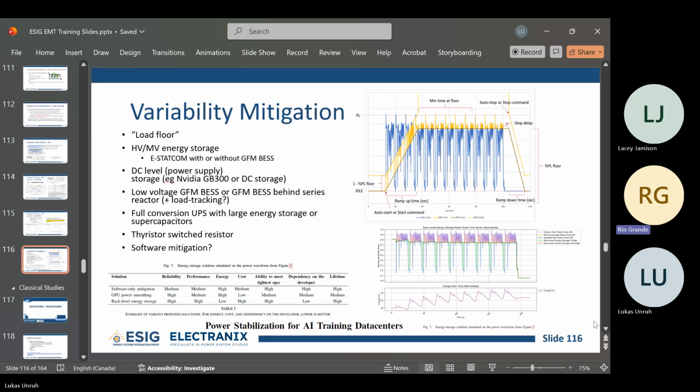I went through a bunch of IBR data through the alert process, and you'd be amazed how many exactly 74.9 megawatt IBRs there are out there, because the NERC threshold is 75, right? It can make sense, but practically it's better to just say maximize it with a floor. You must do at least this, then we can plan for that. And if you ride through more, it's okay.